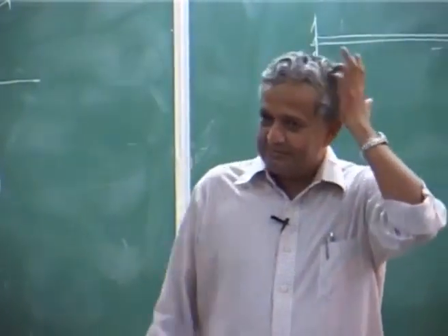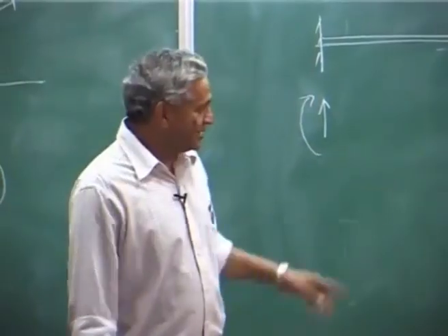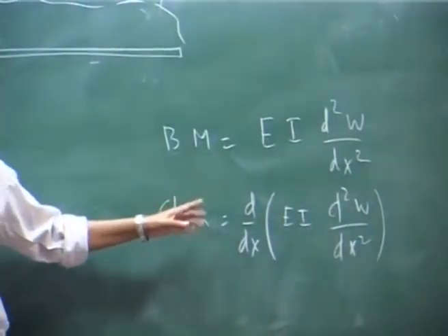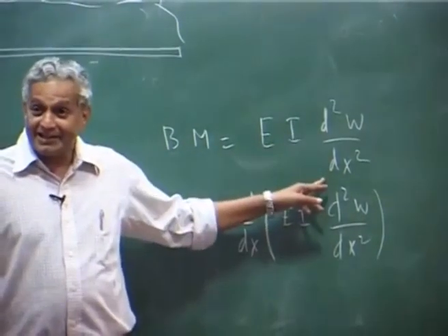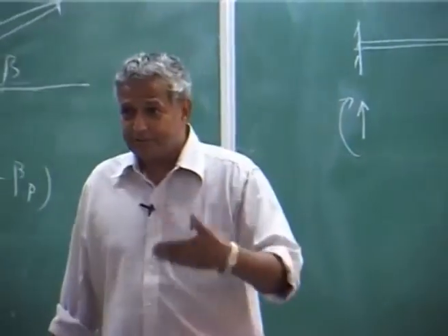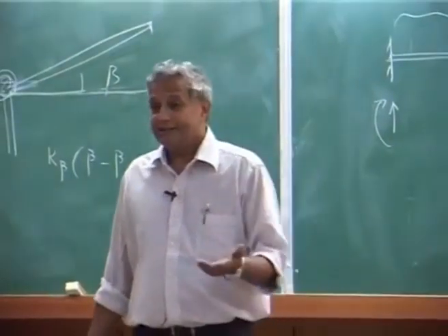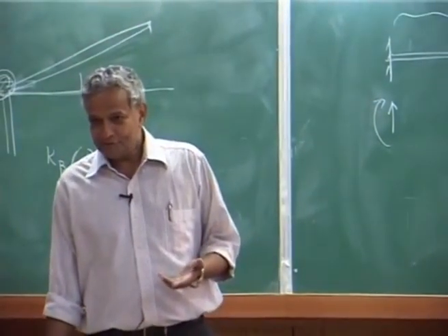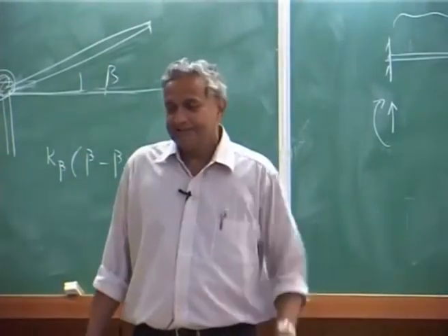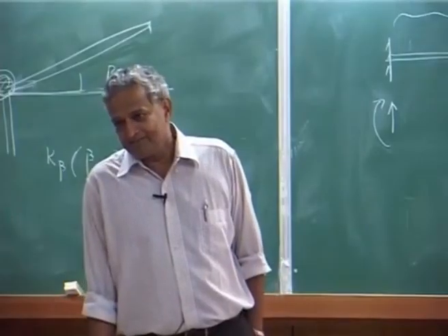So, this is an iterative process. Usually we do not calculate bending moment and shear by this approach, because of the simple reason you are taking secondary, all approximate you are doing numerically. Whenever you do differentiation, you may have error. So, when you want to get the loads, you simply integrate the aerodynamic and inertia.